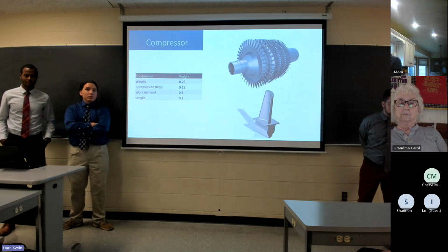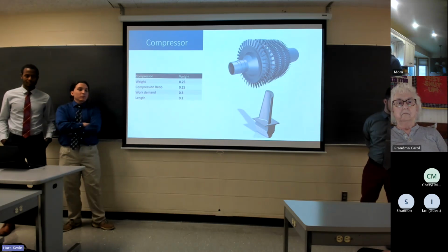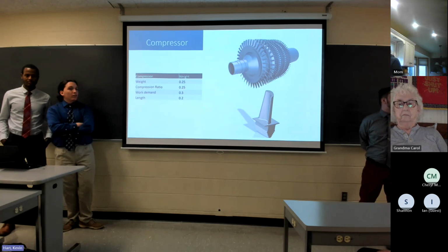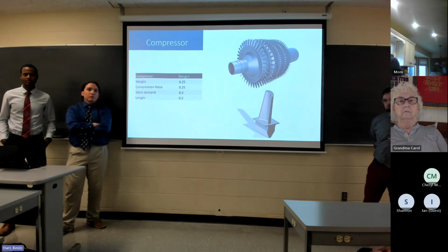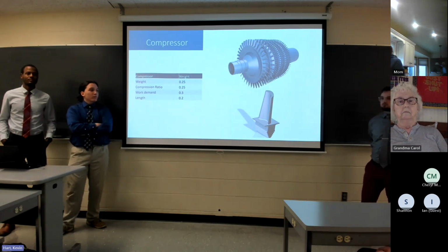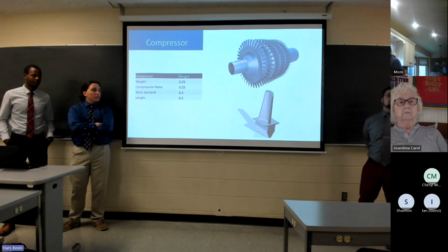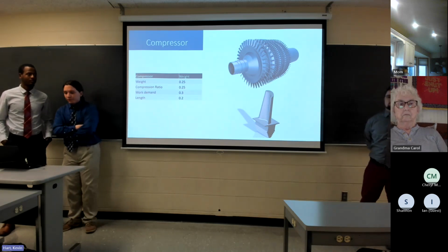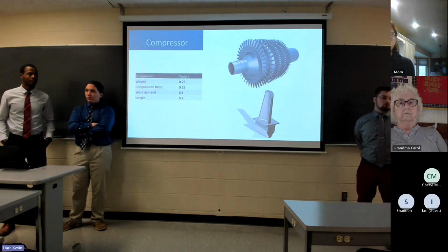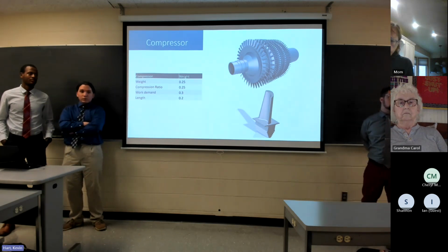How much of the power is derived by the turbine and how much is left for thrust? Any particular numbers, like 50% would be left for getting thrust and the remaining would be diverted to the compressor and other auxiliaries that are needed. Is that part of the constraint or is that something you have to set? No, I don't believe so. So what are you setting? We're going to set the compressor and then size the turbine. Since it has to match by essentially the work, the mass flow, and also the RPM, then you can set the turbine and that ratio would be further defined.